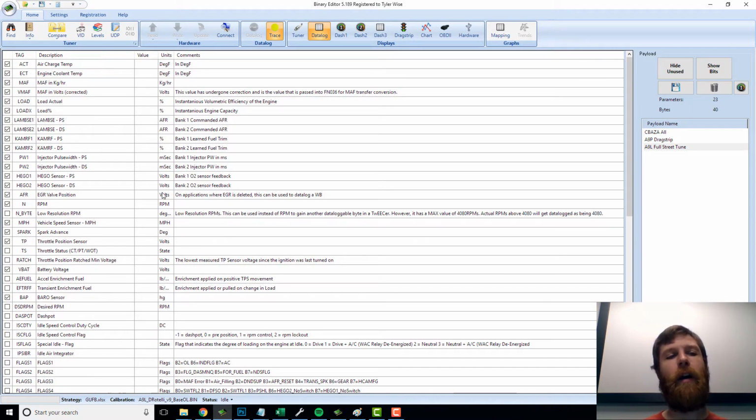So let's say you turn all these things on and you run your data log. Now, there's really kind of three different conditions. When I think about fuel, there's three types of things that I'm trying to tune, and I'm really focused on one at a time. So if this is like a first fire-up combo and you have no idea what's going to happen, you're hoping for the best, obviously you're not going to go beat on the car right away unless you think it's going to be safe. So the first thing that you would want to do is focus on idling. If you can't get it to idle well, it's probably not going to drive well. If it doesn't drive well, it's probably not going to be working well at wide open throttle. So the first thing that you focus on is idle.